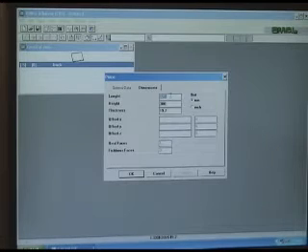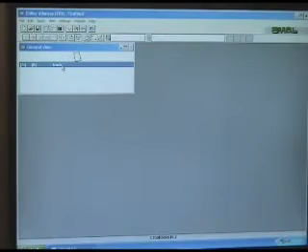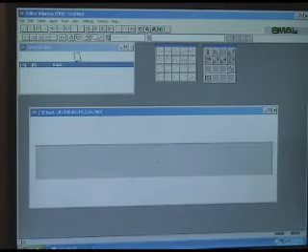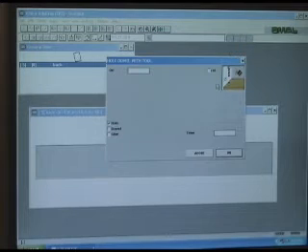Make a rail that's 150 millimeters, and the length of the edge that we're processing, we can program in millimeters or inches. Here's the face, with a number of different ways to insert the drilling and doweling. We'll use single point programming. So the first hole would be 20 millimeters, and we're going to drill, dowel, and glue.